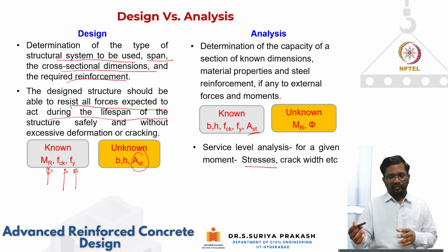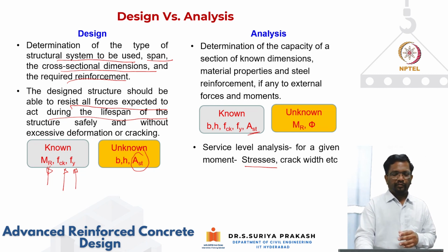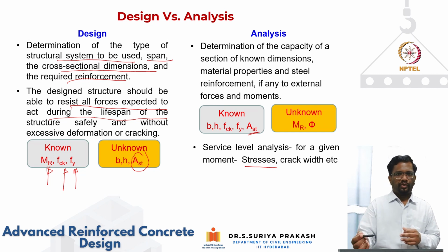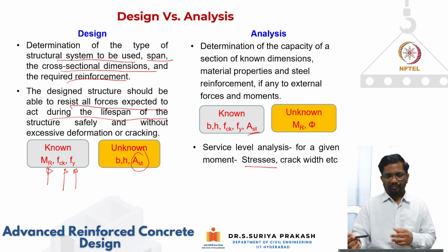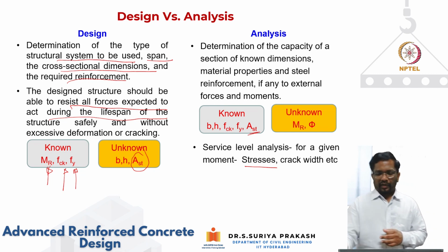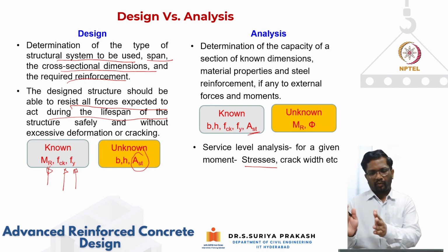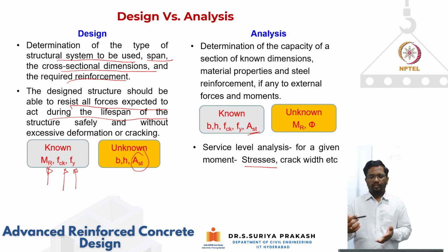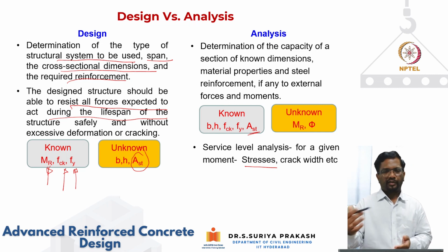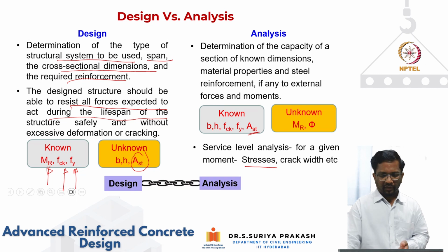Concrete strength and grade of steel will be given. You will end up finding, most of the time, the amount of steel that is required. In analysis, the entire details will be given. You are just going to find the moment of resistance and curvature at failure, or sometimes, for service moment, what kind of stresses and crack width are going to be there, right?